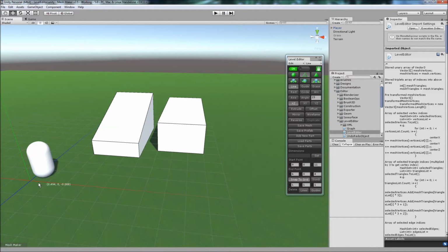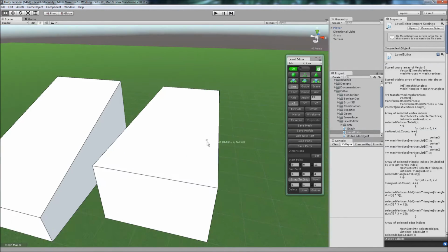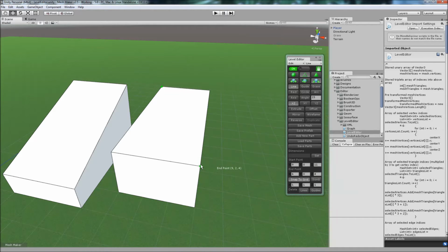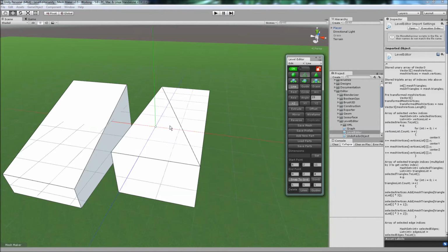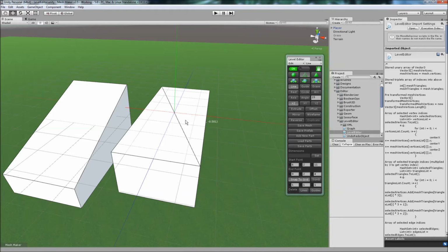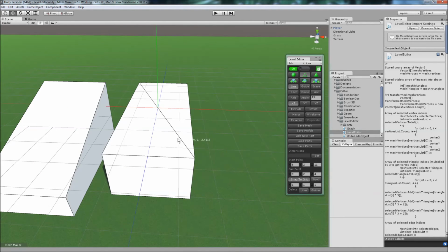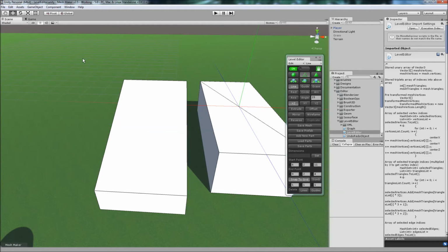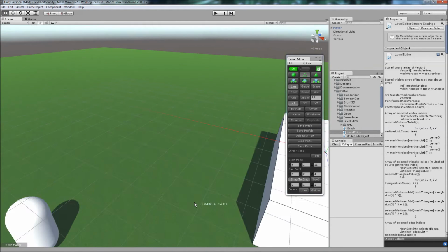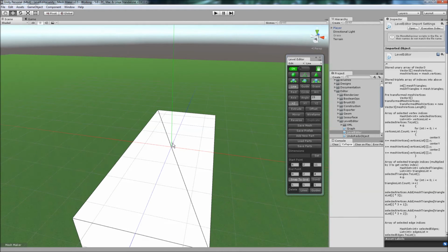And because everything is relative to the pivot point, sometimes we might want to move the pivot point. And the way we do that, first I want to find the center of this rectangle. So I'm just going to draw a line across, and we know that the center point is this midpoint. And what I'm going to do is I'm going to click on this lock icon here, and that allows me to move the pivot point wherever I want. If I hold down the shift key, that temporarily disables snap to grid. And we move it until it snaps onto the center point of the rectangle here. And I'm just going to delete those again. So we have the pivot point in the right location.